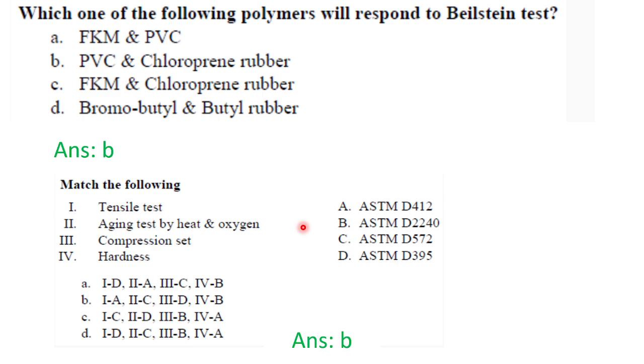And also in case of elastomer, if you need to do UTM or tensile testing, you need some dumbbell type of sample. Yes. Now you also have to have even thickness. There must not be any air bubble formation during the preparation of your sheet.